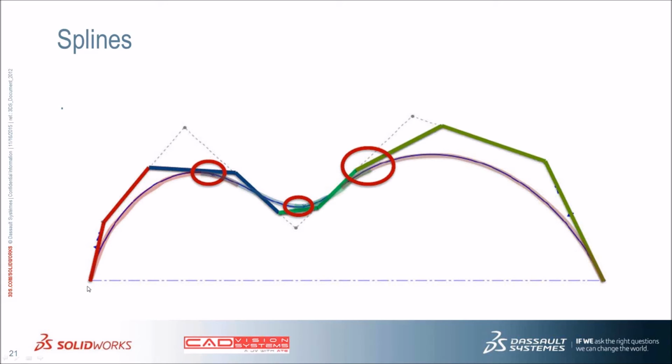The first span is created using the following function, this red line, which actually extends under here too. Then SolidWorks will generate for the second span the blue colored line, here overlapped by green. There's always an overlap here, and the third span overlaps this green here. Having said that, you can see that these are where the control vertices are aligned. By controlling these vertices, we're controlling these invisible functions here, which in turn control the visible spline itself.